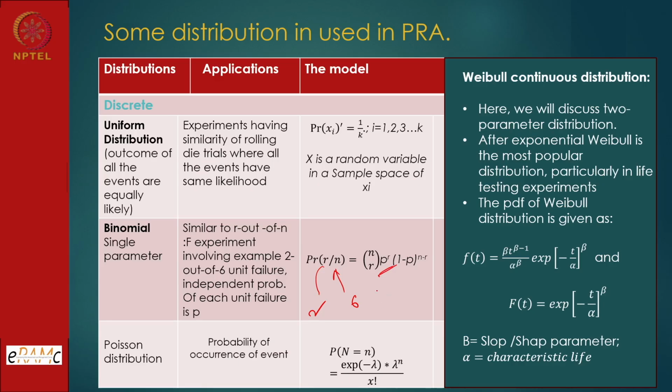The point is that, on pump failure we have collected data, and you found that the probability of this pump failure is, let us say, 2 out of 1000. So, 2 into 10 to the power minus 3. So, this will be P. So, this is an individual component characteristic.